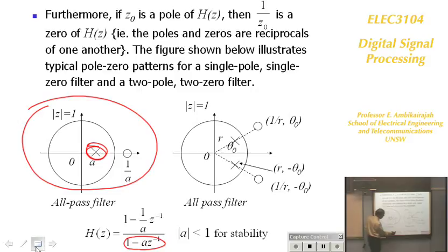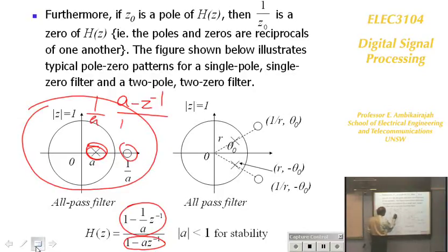And you have to make sure the gains are matched. So then this is reflected here. The pole is reflected into a zero. If you do that, that's your transfer function. Now if you simplify the transfer function, what you would have is a minus z to the minus 1 divided by 1 over a, leave that constant, 1 minus a z to the minus 1.